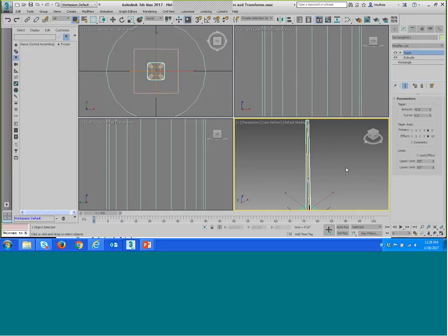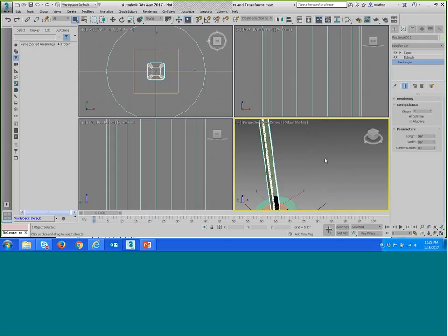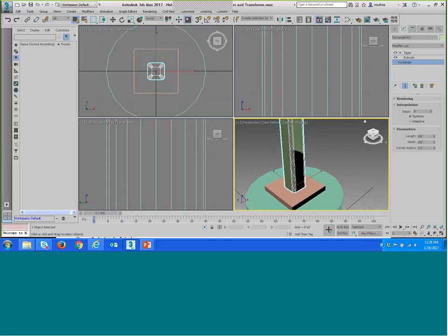Now in this case, I can still go back into the rectangle or the extrude modifier and change those, whatever the amount, maybe change the height. So you can still go there, and you can even modify the parameters of the rectangle shape. So for example, given steps of 5, you can see the change. I will first zoom into it, and it has already taken up the 5 steps in the interpolation. I can also now go back and give 2. So you can still go back in the modifier list.